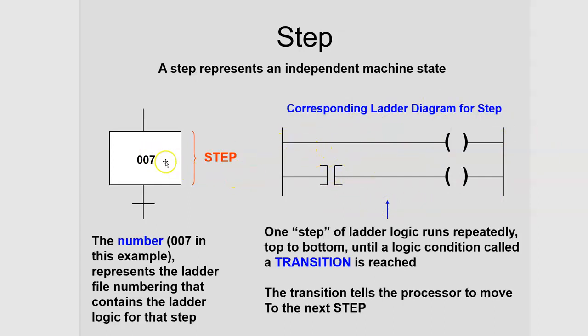But here, I go inside of here and I have, well, the fact that I don't have an instruction here means that as soon as this is run, this right here automatically is true. It turns on because this is a non-conditional run. But when this turns on and we scan this next line, if this is true, then it'll turn this output on. And so you can imagine other lines of code, other rungs here.